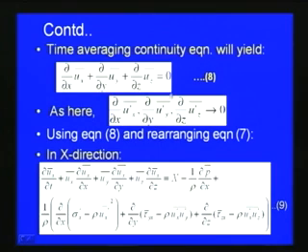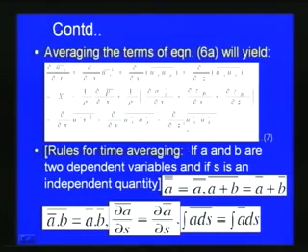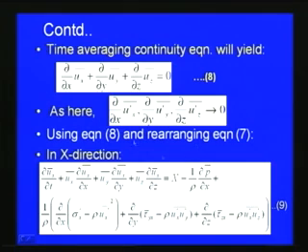Now, if we use this continuity equation 8 and the time averaging concept, we can rearrange the earlier equation number 7 into this form, equation number 9. Finally, in the x direction we can write ∂ū_x/∂t + ū_x ∂ū_x/∂x + ū_y ∂ū_x/∂y + ū_z ∂ū_x/∂z = X − (1/ρ)∂p̄/∂x + (1/ρ)∂/∂x(σ_x' − ρu_x'²) + ∂/∂y(τ_yx‾ − ρu_x'u_y'‾) + ∂/∂z(τ_zx‾ − ρu_x'u_z'‾), where X is the body force.